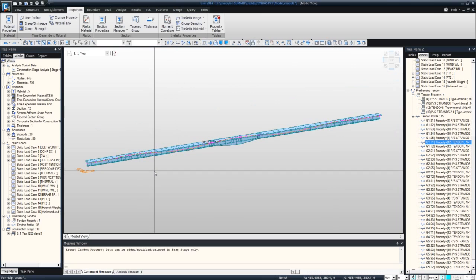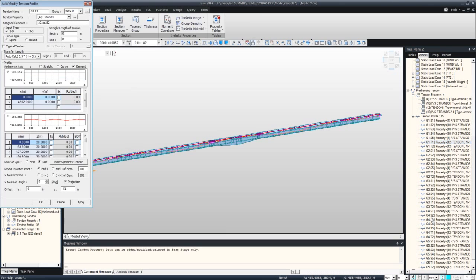And then 2 post-tensioning continuity strands that go from one end to the other. Open up the properties of the strand. So when we put the strand in, model the tendon name, select a group. If we need to put that into a group, I usually just leave them out of the group and just apply them as loads.